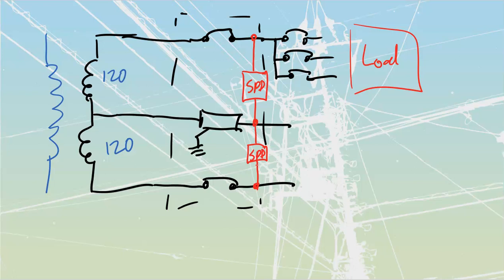Because a lot of what happens is going to be stuff that comes from outside influences like switching transients or lightning strikes, and then it's going to try to divert to ground in a lot of cases. That's where lightning is actually trying to go. So if I take a look at my surge protective device, if for whatever reason we were to get some increase, that we have a lightning strike out here that hits my primary line, that's going to raise this value of voltage.